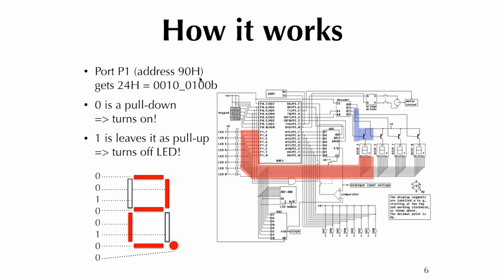Those are general purpose registers. Or in MIPS, they get $0, $1, and all those things. Well, they don't have to be all general purpose. They can be special function. What that means is they don't just store values, which is what a regular register does. A general purpose one stores temporary values so that you don't have to go to memory each time. Now, a special function register stores a value but causes a side effect. What kind of side effect? Well, in this case, the side effect is you set the pin to be high or low voltage based on whether you write a 0 or 1 bit.